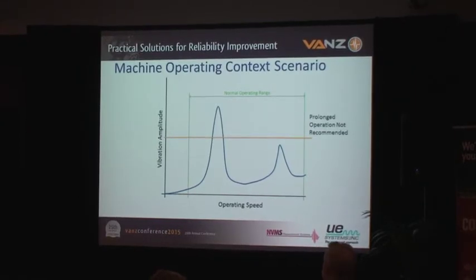What the manufacturer says, basically, is you really need to avoid that area by the first critical speed, simply because running at that kind of an amplitude, we don't want you to do that, we're not going to warranty it. But really what I was hoping to do was, there was the absolute thou shalt not exceed value.